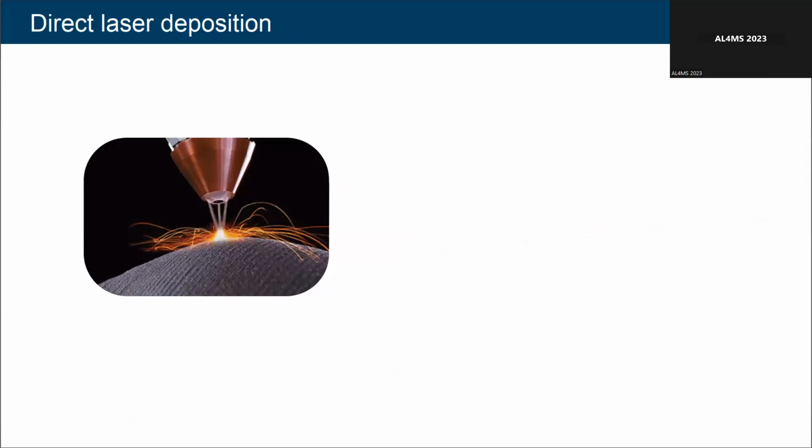In this instance, they were interested in direct laser deposition, where if we look up at the slide, we can see coming out of the nozzle here, these 3 jets of metallic powder being blown onto the component. And then down here through the middle of the nozzle is a laser beam outside of the visible spectrum, which is melting that powder locally onto the material.